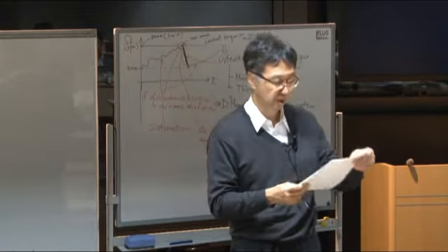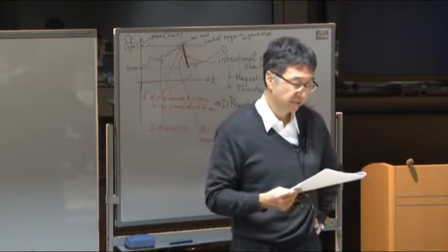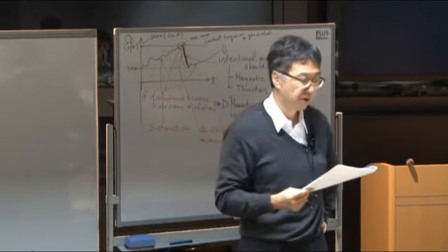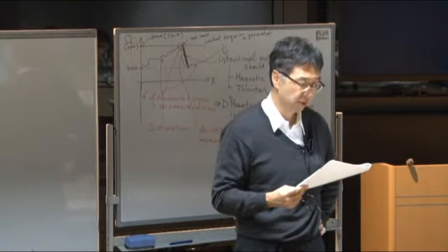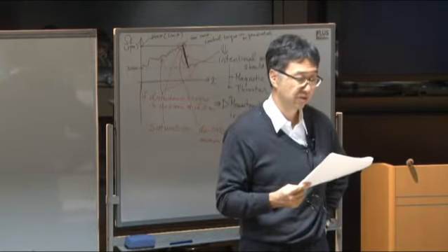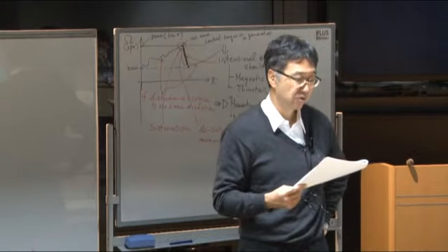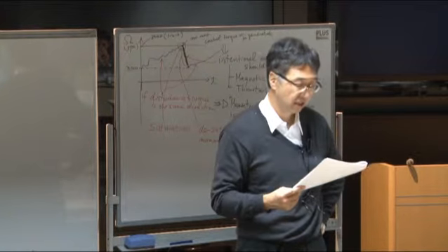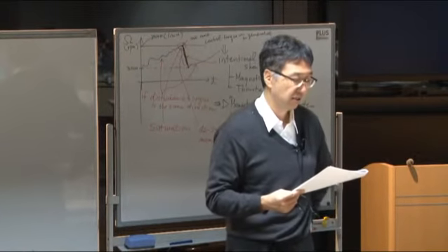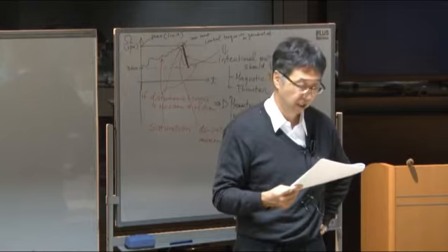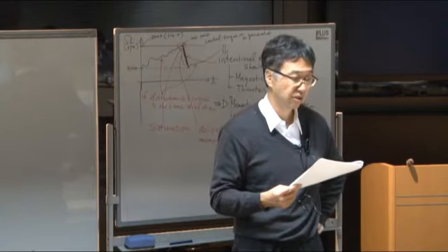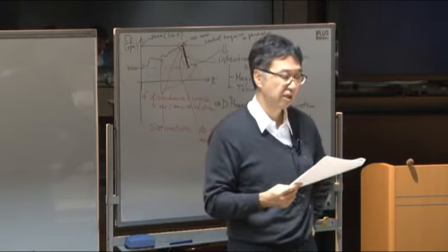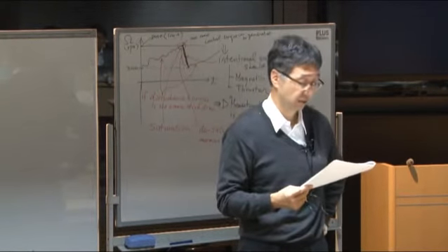Okay, let's go to the next one. This is an example of the thruster system. I didn't tell you very much about that. The upper part is the performance of different kinds of thrusters, and the value shows the Isp, specific impulse. If you have a higher value, then you can get larger delta V with a small amount of fuel. For example, the ion thruster is the maximum, with a very large Isp of 3000.